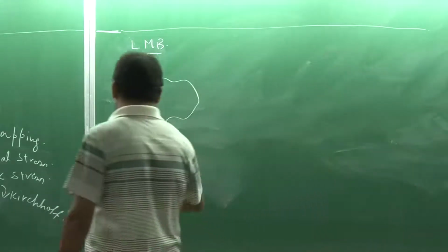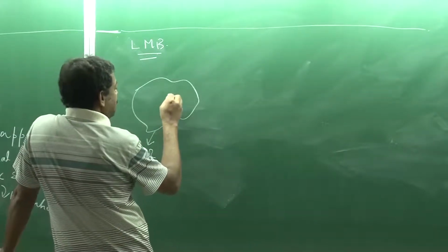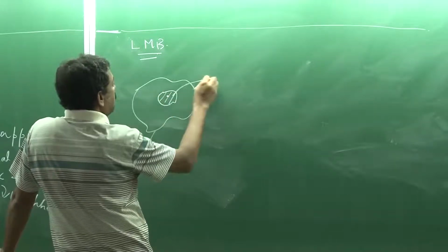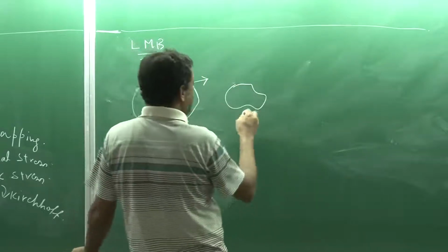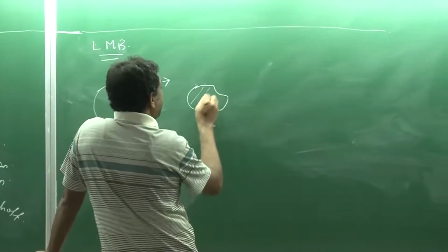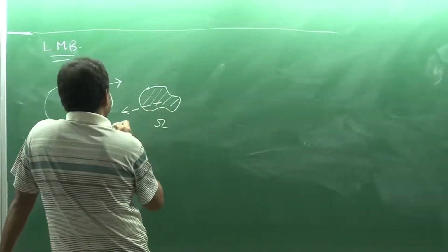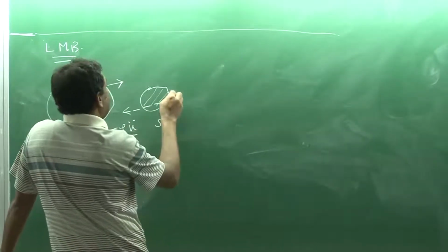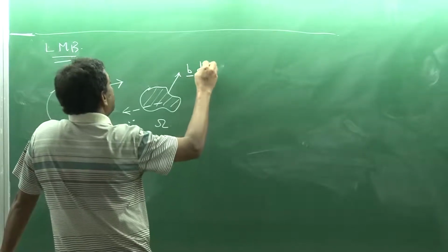So, this is the deformed body, and on this body I am just considering a point and a subdomain. I am separating out the subdomain, and in this subdomain, what are the forces that are acting? The force that is acting is the inertia force, minus rho u double dot, and then a body force, b bar dv.